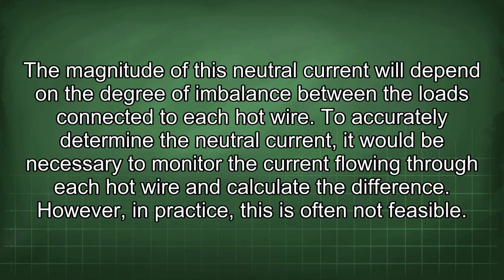The magnitude of this neutral current will depend on the degree of imbalance between the loads connected to each hot wire. To accurately determine the neutral current, it would be necessary to monitor the current flowing through each hot wire and calculate the difference.